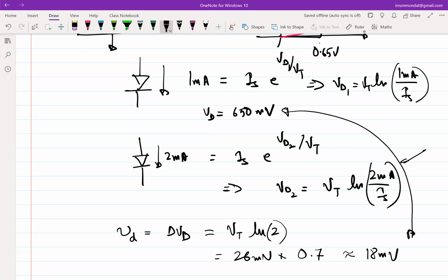There is certain assumption that goes in every engineering discipline. So in this particular course, we'll assume that it's 650 millivolts, right? But you will have to keep it at the back of your mind that going forward, if you take up circuit design as a career, don't make this mistake of always assuming the diode to be 650 millivolts. Or rather, even the 650 millivolts number is particular to certain types of diodes. Depending upon how it has been constructed, even for the same ranges of current, you can have different diodes with different voltages, which are generally called cutting voltages, right?